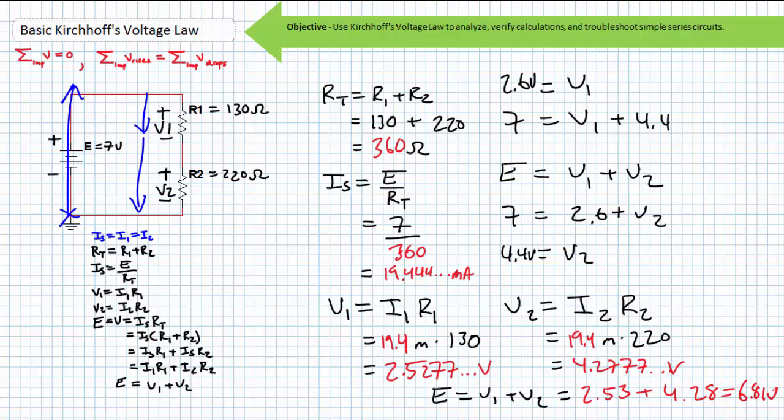What if we went about this in a different manner, though? Let's say we calculated the voltage drop across V1 using our wrong source current, and then just jumped to KVL. V2 should be equal to approximately 4.47 volts. But it isn't. How do we know it isn't? Ohm's law is now used to check KVL. Even using our incorrect source current is not in agreement with our KVL analysis. Again, we are keenly aware that something is wrong because the results are not in agreement with one another.